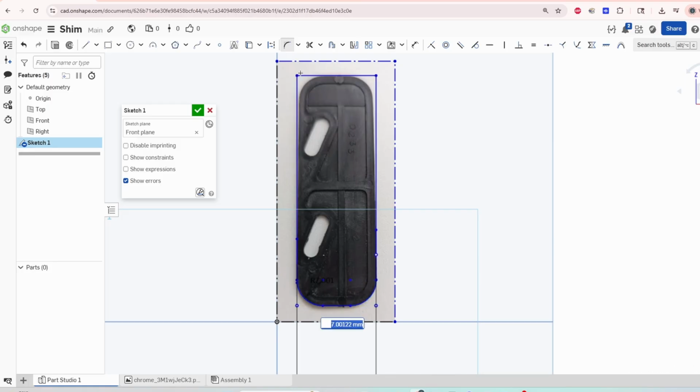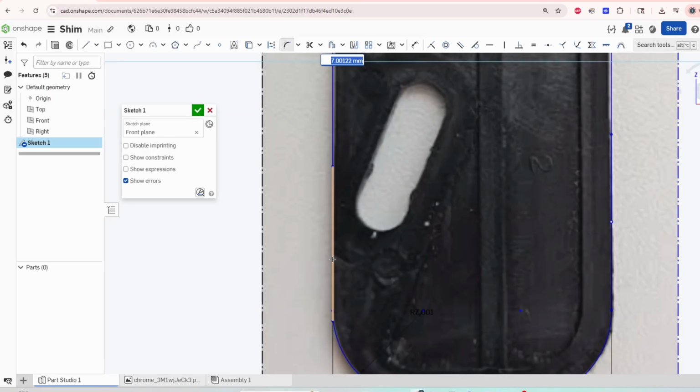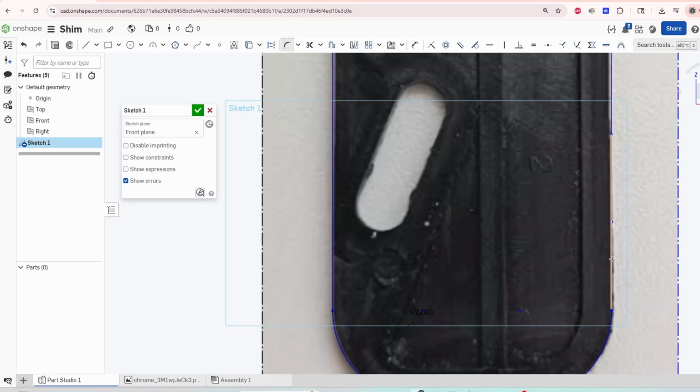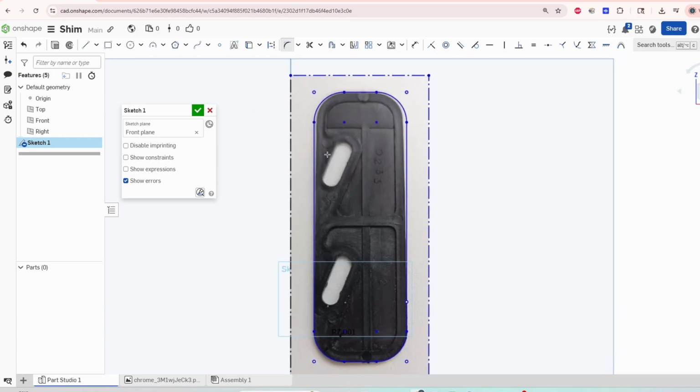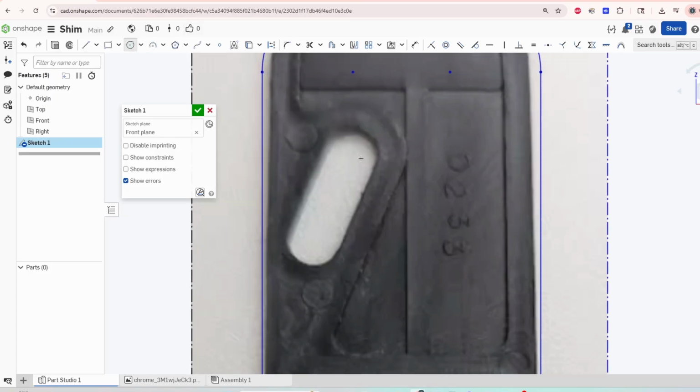click outside, and it's making those fillets for me. We're going to keep that the same. Yes, everything looks good. Notice it's not following exactly. That's fine, no problem. And we can get rid of this extra edge right here. So let's click that edge, delete, click that extra edge, delete. Now we're going to go over here and build this right here. So we can go with circle. We're going to build a circle and get it just approximately what it is.